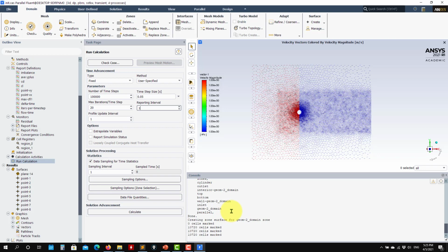And what else I want to do? So also it's something important that you don't have access here, okay? But you can access that in the text user interface, okay? You can set up the maximum flow time. So by default, the maximum flow time is whatever is infinite, no? It's whatever combination you have here. So here you multiply this by this, it will be like 1, 2, 3, it will be 500 seconds, okay?